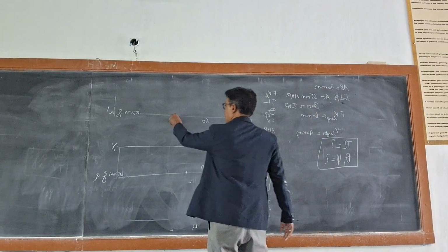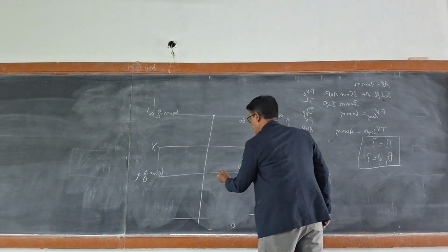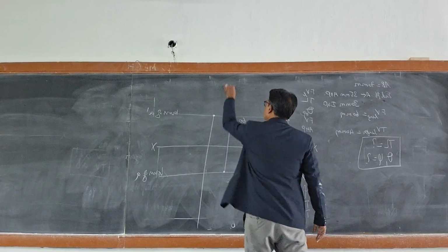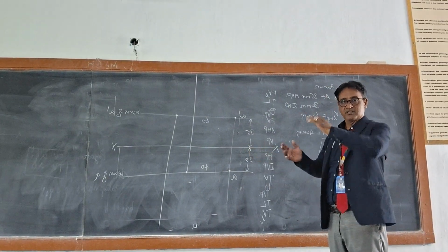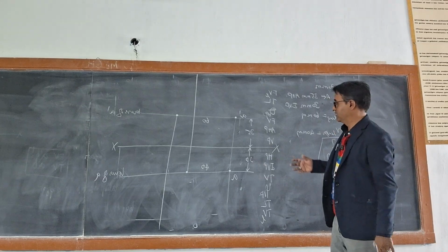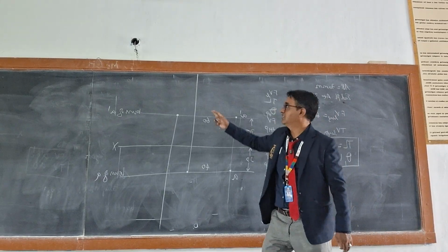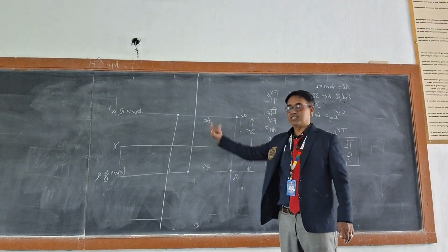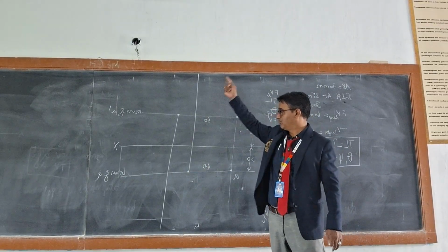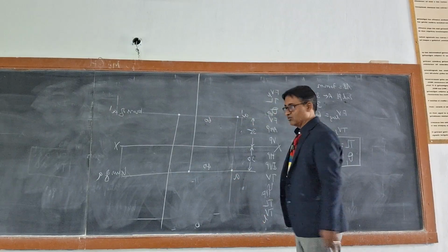So now what do I do? I drop down and this up. Okay. Next step is the reverse of the basic problem which we have seen. Because there the true length will be given, therefore you draw the true length and true inclination, then from there you drop down. But here you have the view length, therefore you have to go vertically up and then you have a drop. And after that, what is the true length?